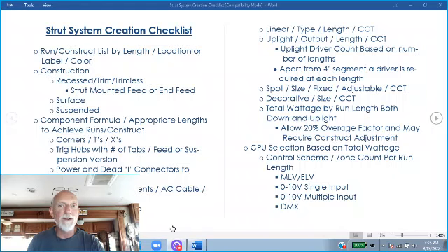So we might be able to get to 22 feet in length on that long side, but on the short side we're going to be off by 1 7/8 inches no matter what, because you have 1 7/8 inches in the width dimension of the fixture you installed in the long side to fill the channel all the way to the end. So you need to take the time to look at some of that dimensional information so that you can get as close as you can to what's being requested, and make sure you can educate your client as to why we can't give them 22 by 16, or 22 by 9.